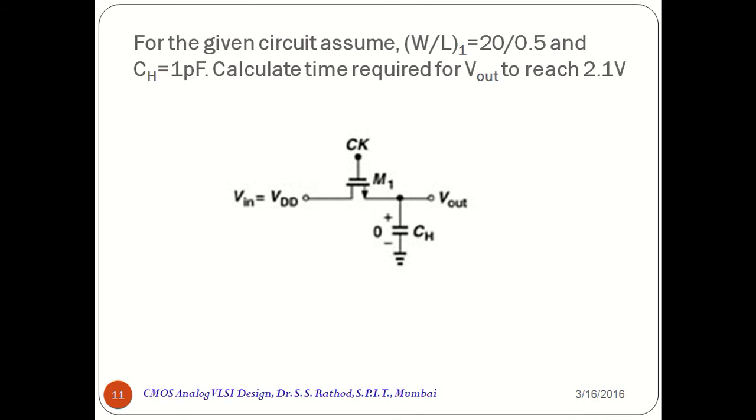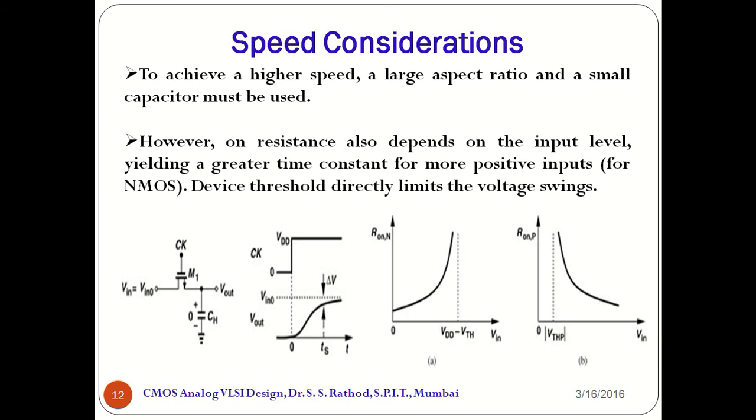Similarly, a PMOS transistor fails to operate as a zero offset switch if its gate is grounded and its drain terminal senses an input voltage of VTHP or less. In other words, the on resistance of the device rises rapidly as the input or output level drops to VTP above the ground in the case of PMOS devices.